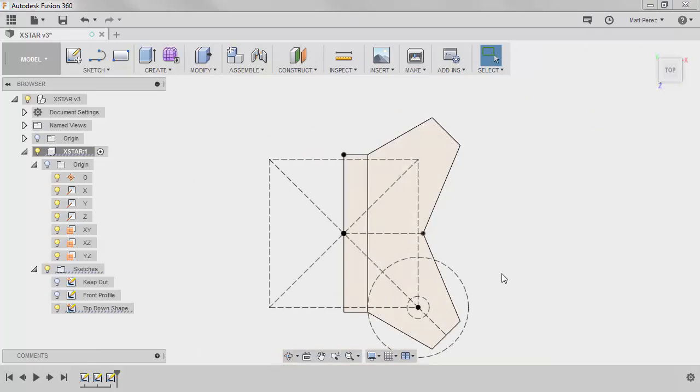There are a lot more elements that we need to add in, but at this point in time, I'm going to break them out into different sketches. Now the reason I like to do that is because when I go back to make edits or changes, sometimes it can get overwhelming to see dozens and dozens of constraints and dimensions and all those things. So it really helps me to come back after the fact in a separate sketch and just project geometry as needed.